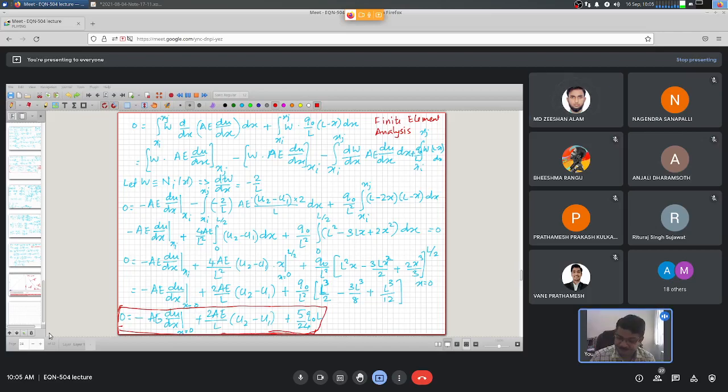Okay, yes, Ishan. So in case of approximation of 1 degree for cubic polynomial, we can also have the quadratic as a function as approximation? Of course, you can. Or cubic. Yes. But the only problem is your problem size will also increase. For quadratic, you need 3 nodes in an element. For cubic, you will need 4 nodes in an element. So that means your number of degrees of freedom are going to increase, your problem size is going to increase. Yes, sir. So that is the only downside.